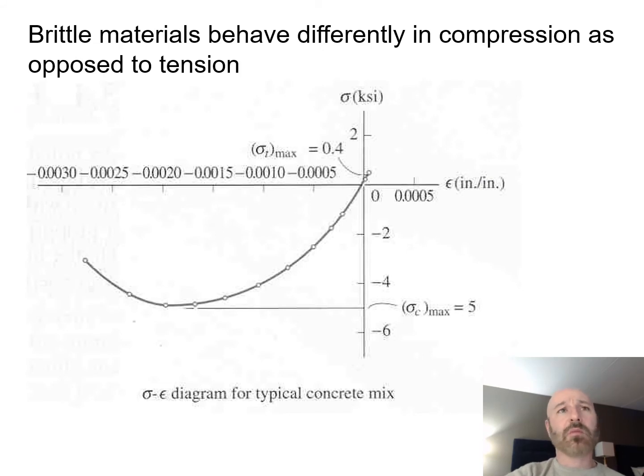So going back to our brittle materials here, one thing to consider here is that brittle materials are going to behave much differently in compression as opposed to tension right there. So sometimes we're talking again back to the concrete that I was talking about there, how I said there was a couple instances where we actually embedded some rebar into the concrete there so we could take a look at what the tension did on our samples for different types of concrete as compared to what the compression test, the standard compression tests were doing.